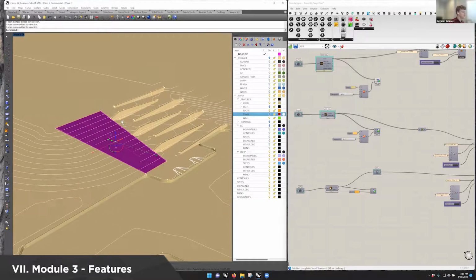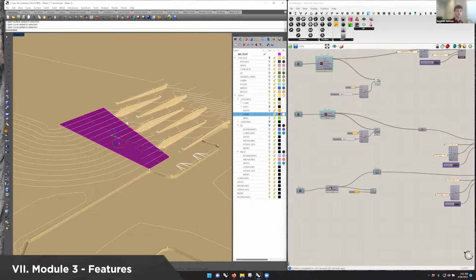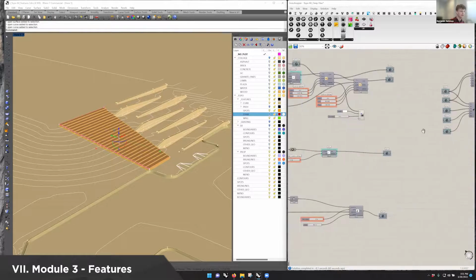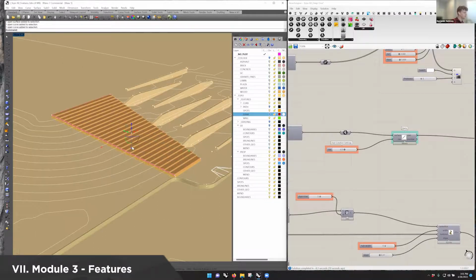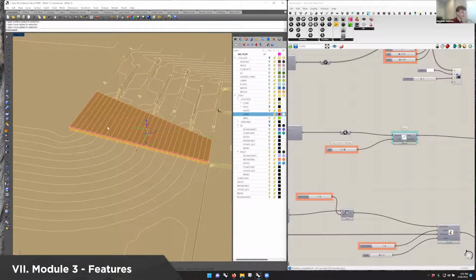But again, the way to think about this is it's about grading. It's about finding those grade break lines for your staircase. So you have a nice preview of what the stairs will look like, and you can define the rise of each step, and I believe the default is 0.5 as well. But the run of the steps will be determined by how long the surface itself is. So it'll create stairs for you, and the run will be based on that. So using a 0.5 rise, it will change all the stairs to match the length of the surface.